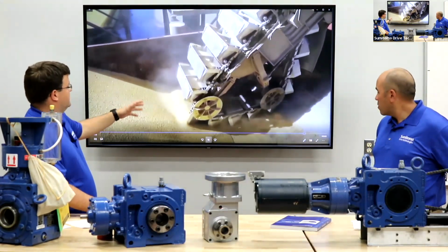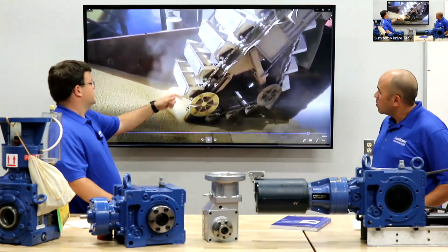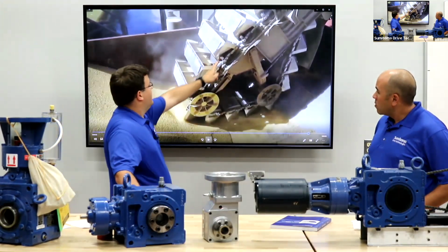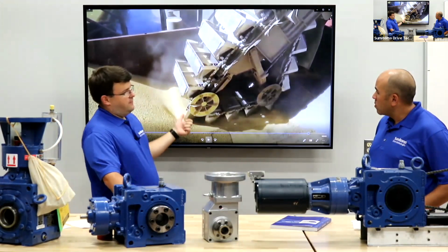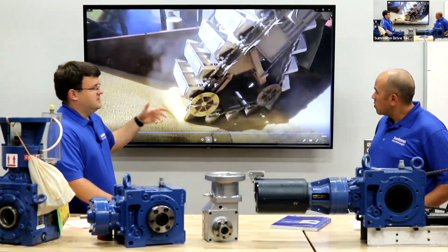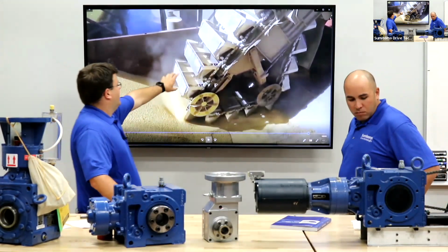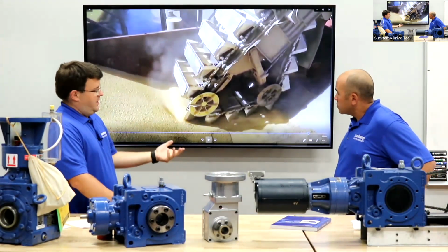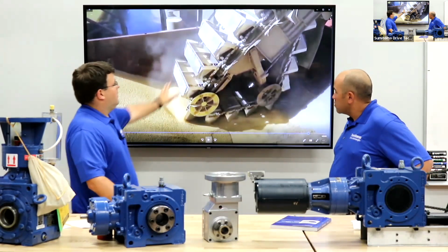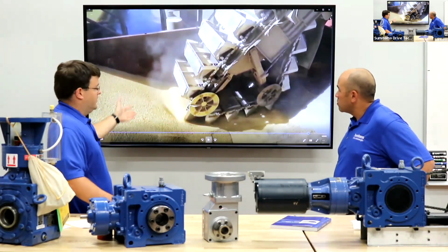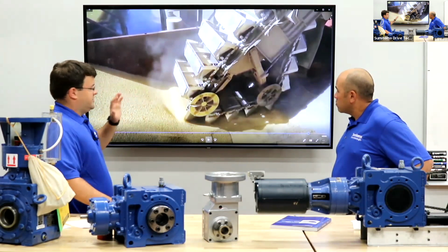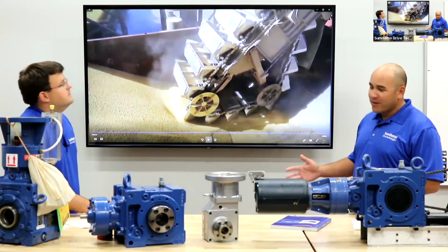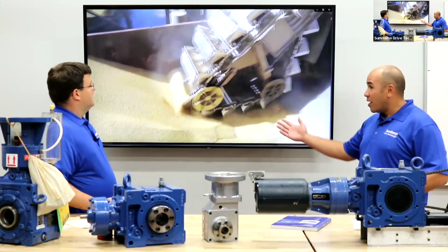This is a bucket elevator, what we call it. It looks like a conveyor in the sense that it goes around pulleys, but we have a chain and sprocket that pulls it around. So every time one of those chains hits the sprocket, it shocks the gearbox system. Every time one of these buckets fills up with whatever material, that's extra weight on the gearbox as well. So all of that has to be taken into account when you're making the gearbox selection. It's not just as simple as speed and ratio. Sure. So a lot of different factors when it comes to the application itself.